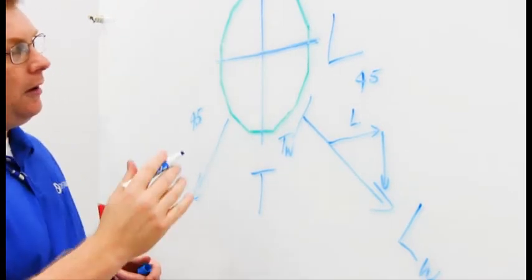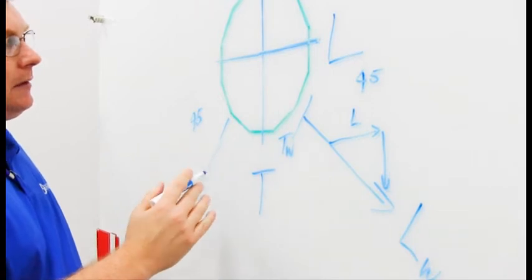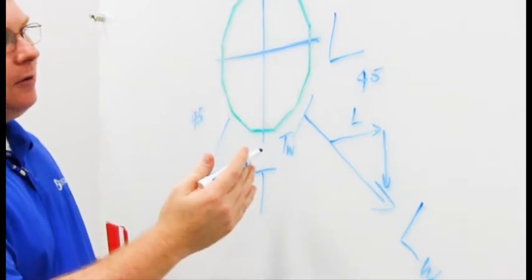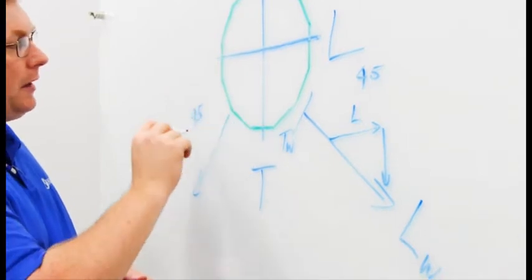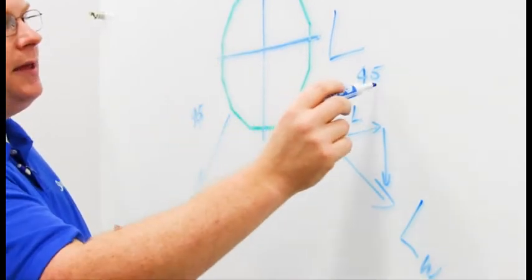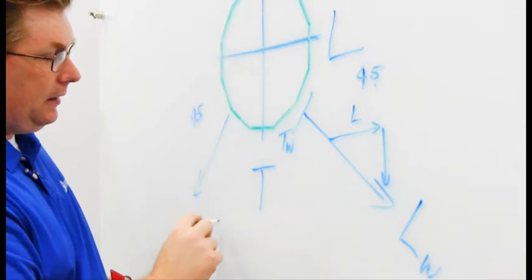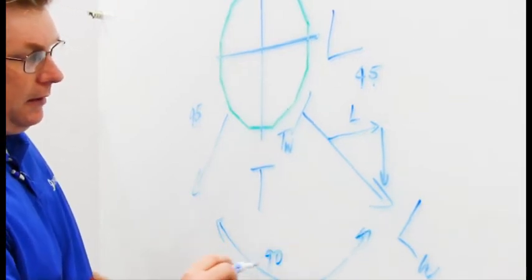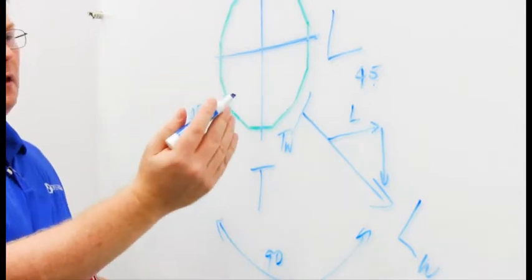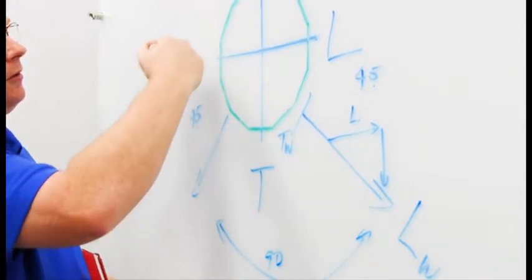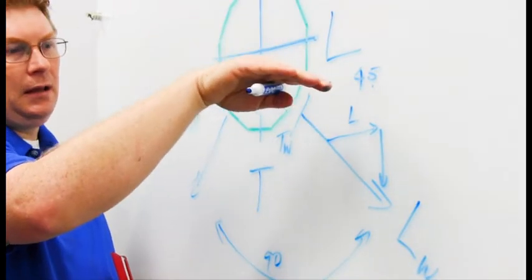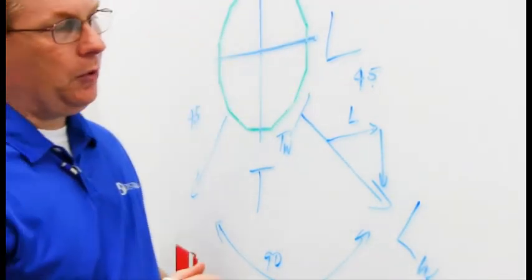And just to let you know, a common mistake a lot of people make is this is a 90-degree turning pole. This is a 90-degree turning pole because this number and this number add up to 90, not because this number is 90. That's wrong. If it's a 20-degree turning pole, the wires are coming off at 10 and 10, like that. Just wanted to point that out.